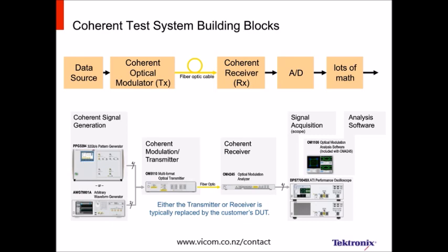And for that, we use an optical modulator, an IQ optical modulator that's going to move that electrical data up onto the optical frequency. And now we have our optical test signal. So if you were going to test a receiver, you could possibly now use this golden transmitter to test the performance of your receiver under different impairments.